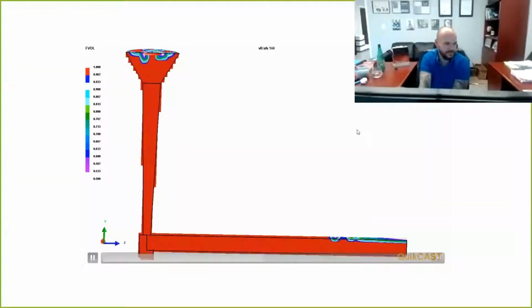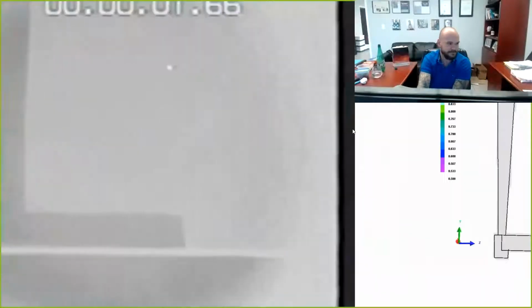Because what happens is, if you've got no combustion, the sand can't break down, and the binder's not going to burn up, and you're not going to get grains of sand. And furthermore, if you can create a running system where the metal is pressurizing the running system itself, nothing can fall in it. And we're going to see slides that show that here in just a second. All right.